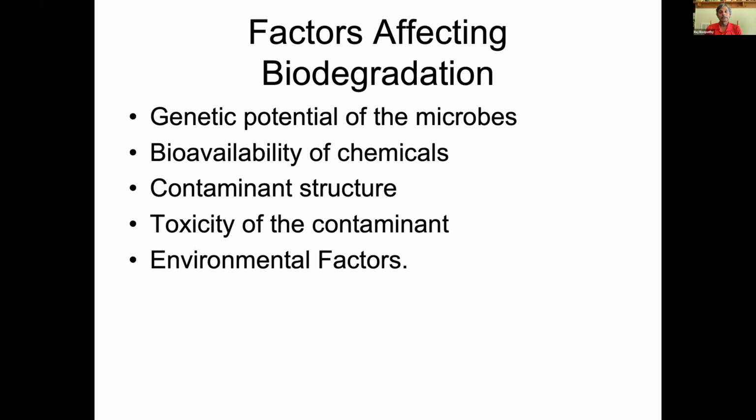Some of the biological factors are, as I said before, the genetic potential of microbes. The microorganism has the right genes to induce the right enzyme. Then bioavailability of chemicals. The chemical itself should be available. If it is absorbed into a clay layer, it's not bioavailable. The microorganism is not going to spend a lot of extra energy to make it bioavailable. Then the contaminant structure itself can be a problem, and then toxicity of the contaminant, and then environmental factors that dictate the degradation rate in the environment.